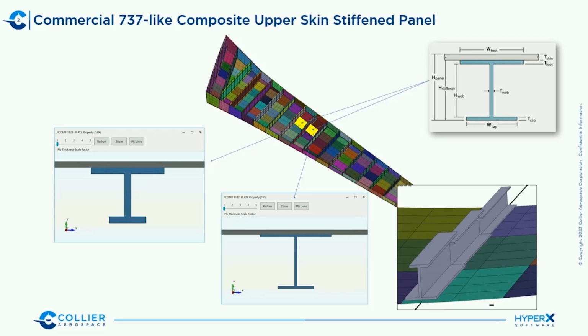It's a challenge, then. You can't take that to your designer, or you can't go to the factory floor and say, make me this stringer. And this problem actually continues. If it were composite, the challenge would be, what mandrel do I come up with for my tooling? Because you don't want this variation in your tooling that you are using to lay down the composite. In addition to that, you have all these ply drops and adds going from a very thick laminate to a very thin laminate.